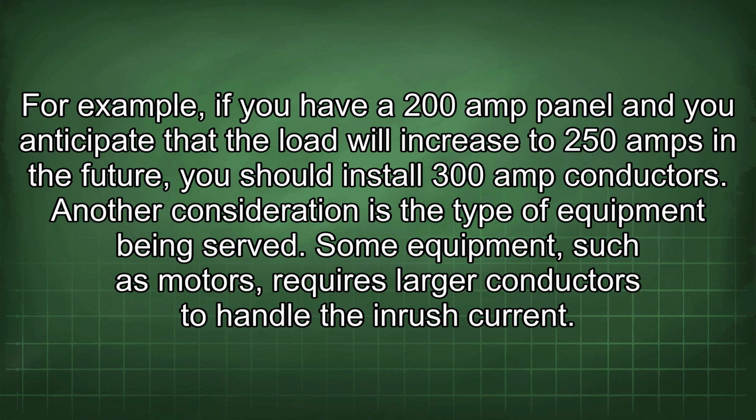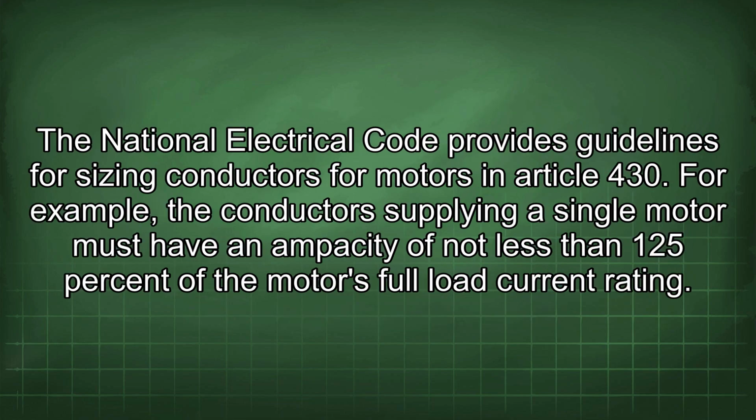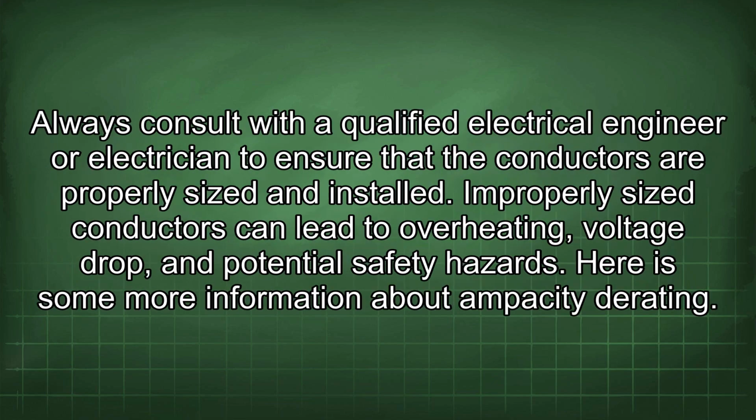Another consideration is the type of equipment being served. Some equipment, such as motors, requires larger conductors to handle the inrush current. The National Electrical Code provides guidelines for sizing conductors for motors in Article 430. For example, the conductors supplying a single motor must have an ampacity of not less than 125% of the motor's full load current rating. Always consult with a qualified electrical engineer or electrician to ensure that the conductors are properly sized and installed. Improperly sized conductors can lead to overheating, voltage drop, and potential safety hazards.